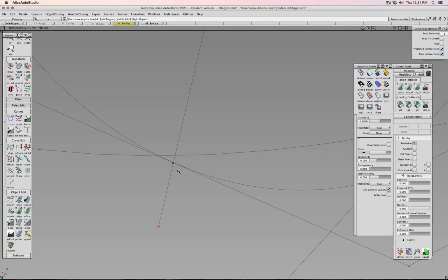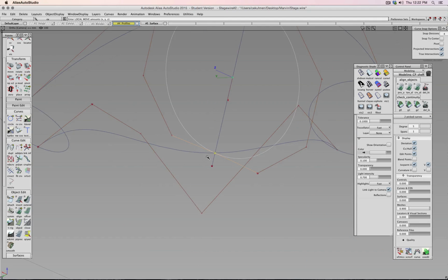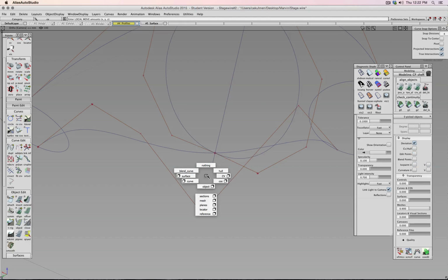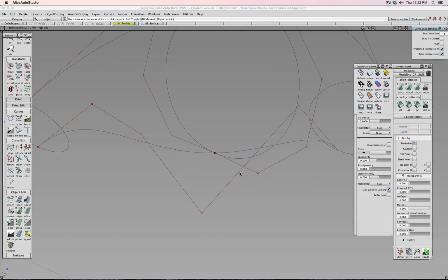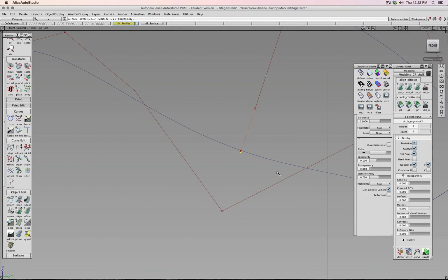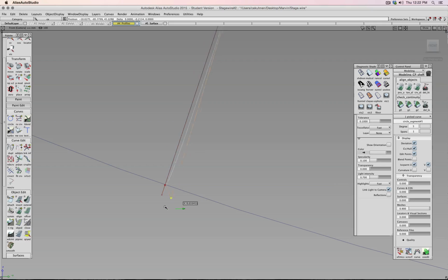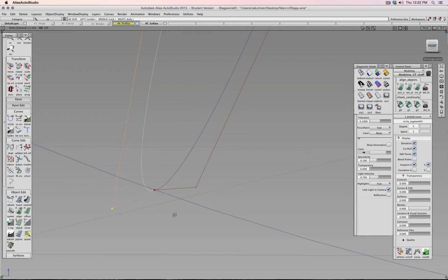So CV, those 2 points, move Alt Control along this line, and then see there is a red cross, there's intersection, and now those points perfectly sit on this path. But now those lines are not tangent anymore. Now I could either do this with a command or do some simple push and pull. So I go to side view of the graphic and, for example, say middle mouse, move middle mouse button and press Control. See, it snaps to this point. Right mouse button, move. No.